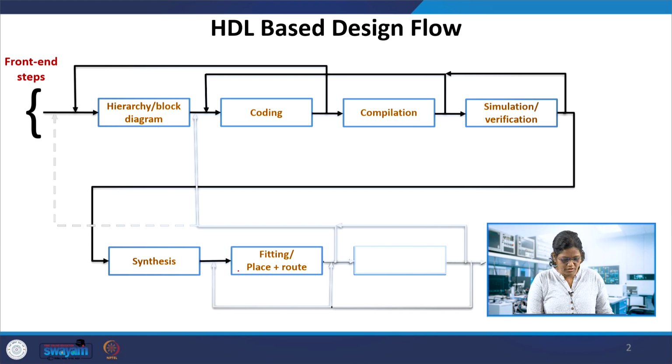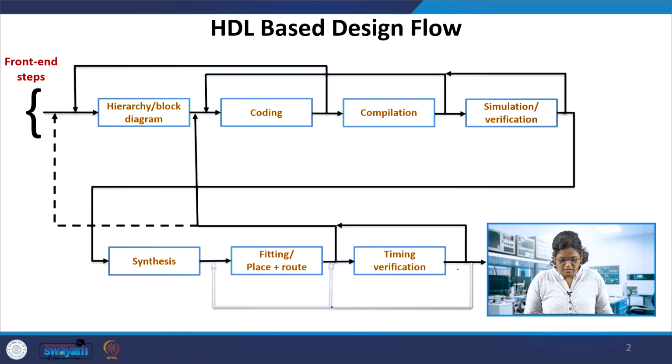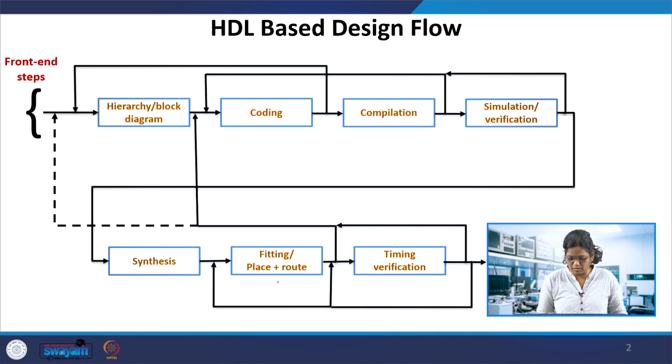In this case, after synthesis, you have the fitting and place and route, depending on the targeted FPGA, and the timing verification is also done. While doing the timing verification, the functionality can also be added a little bit and checked, but usually functional verification and timing verification are mutually exclusive. If there is anything wrong at that stage, yes, we have to go and correct it from the first stage. Otherwise, the fitting and the place and route is possible.